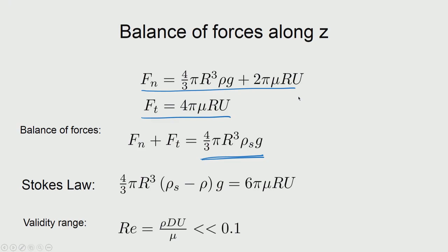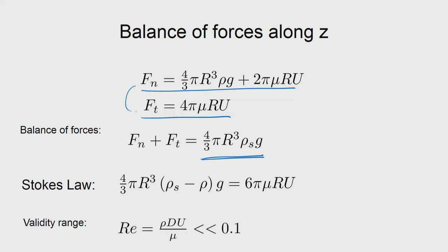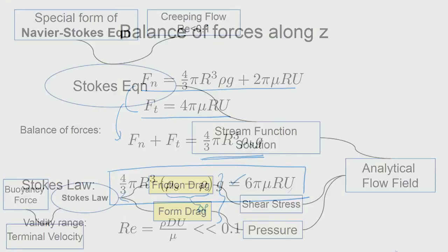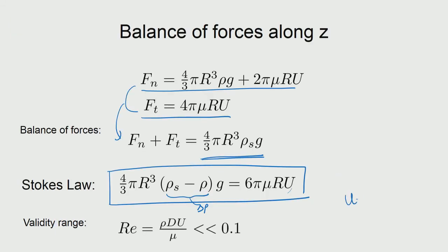Alternatively, the fluid is actually moving upwards and the solid is stationary. So it is only relative velocity that we are looking at. So when you put these two and substitute into this, then you can get this equation which tells you that, of course, this can be taken as delta rho. Which basically tells you that because of the density difference, the buoyancy is actually compensated by a force, and that force is actually going as 6 pi mu into r into u. Now this u is then called as the terminal velocity, when this balance is happening.